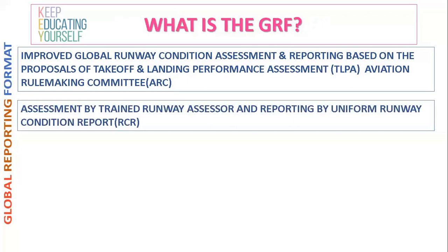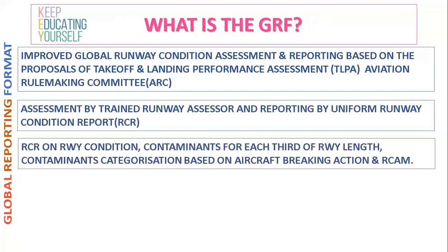Assessment will be done by a trained runway assessor and reporting will be done in a uniform runway condition report. The runway condition report covers runway conditions, contaminants for each third of runway length, contaminants categorized based on aircraft braking action, and the runway condition assessment matrix. We will discuss each in detail.